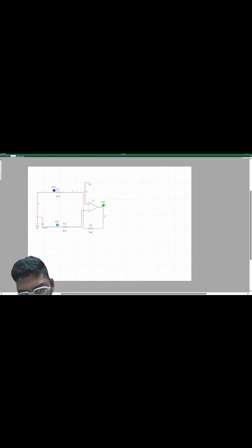Otherwise, the LED remains off, corresponding to the transistor cutoff region. This experiment validates the principle that a small input current at the base controls a much larger current through the collector-emitter path, making the transistor vital for digital control, logic circuits, and automation in electronics. This is how this circuit is built. Thank you.